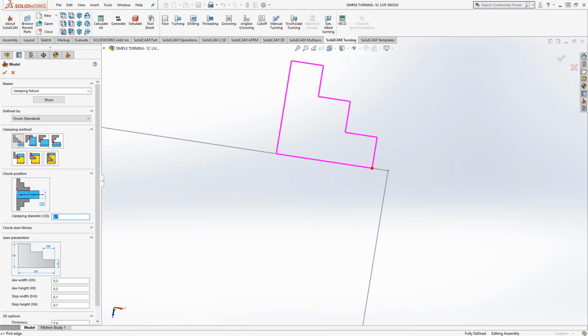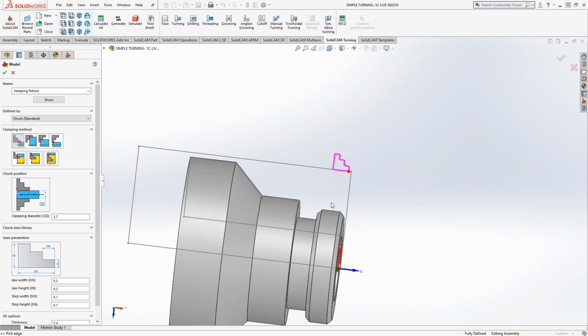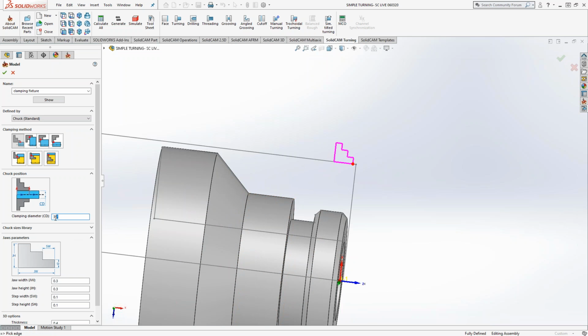You tell it where it's sitting in terms of diameter over here, and it defaults to the diameter of the stock. Right now, I can tell that the diameter of the stock happens to be 3.7. You saw that we did it as relative to model, but if you had put in your stock size using absolute coordinates, then this number should match that number. If you wanted to change where this is being held, let's say once we start doing side 2, and I want to hold it on that diameter, all you have to do is highlight this number and either plug in the number if you know it, or use the geometry to drive everything. You highlight that number, click on a piece of geometry, and you can see that it shifts to that diameter there. I'll move it back by doing the same thing.